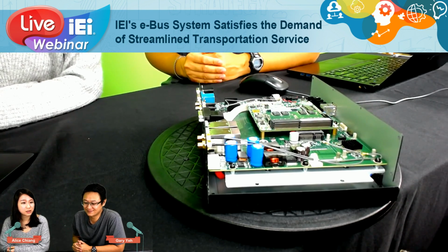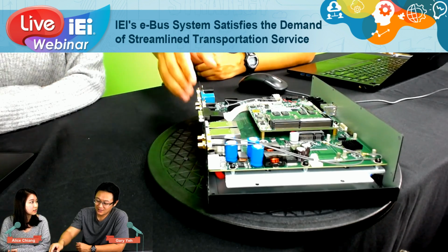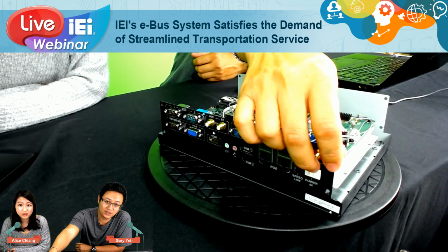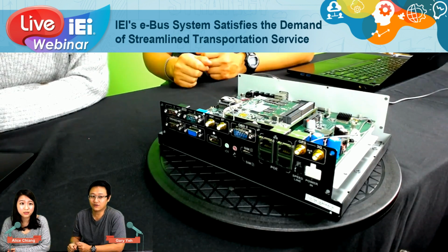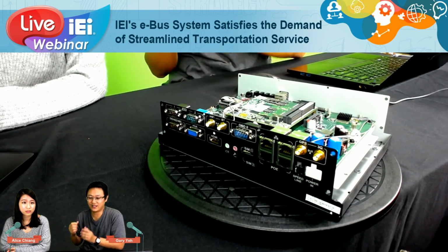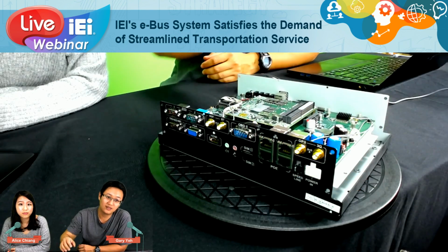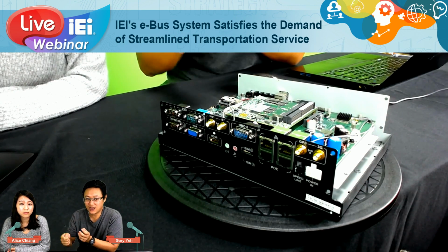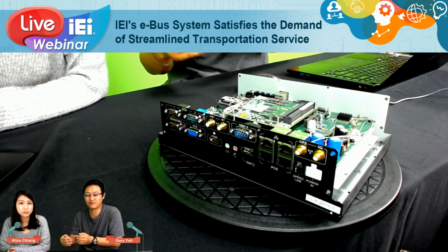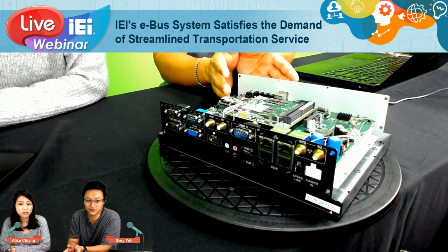Yeah. Okay. So is there any special design for the box PC? Yes, ACC. The ACC port here, because you know when you start the car or vehicle, there is a surge current and that may damage your devices. So we use the ACC pin, and if it turns on, we will delay 10 seconds. Default is 10 seconds. You can change it from the BIOS, and after 10 seconds you will start your computer.